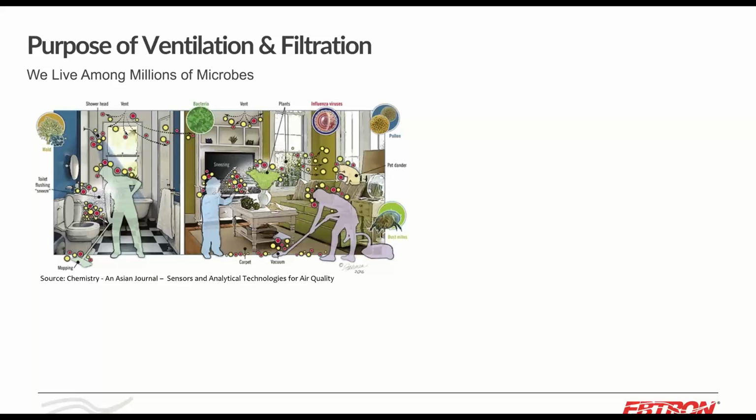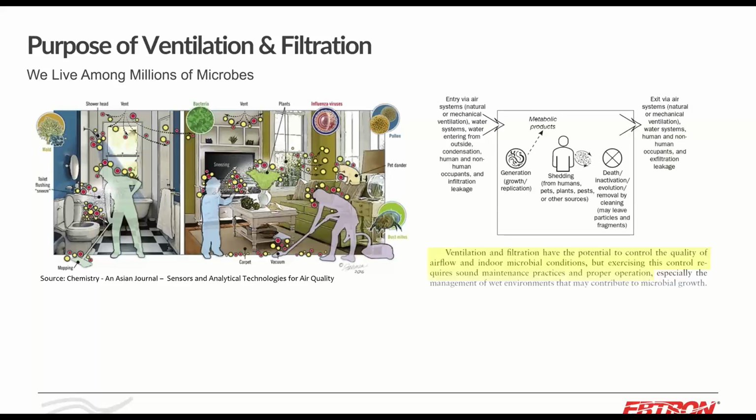It's amazing that in hospitals, there's no requirement to filter the return at the source, at the operating room or at the 6-person room. We only filter the clean air going into the space. A smart person would filter it so the ductwork wouldn't get dirty, and thus other things would stay in that ductwork.